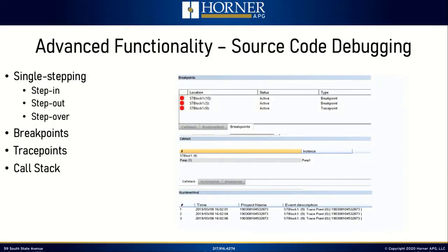We've also got some other new capabilities that we should mention before we wrap things up here. And that is some of the source code debugging that I briefly mentioned when I was talking about simulation before. That is things like single stepping, establishing breakpoints in your logic, so executing a logic and then stopping at a certain point. That's especially useful in things like structured text. Establishing trace points so you can follow variable values as they are solved multiple times within one scan, for instance.